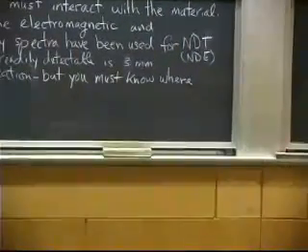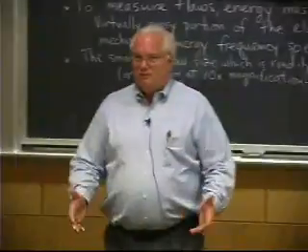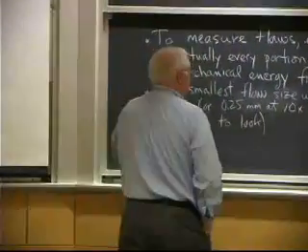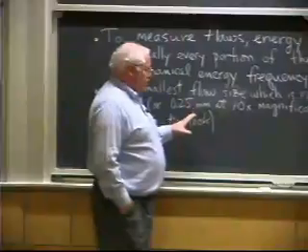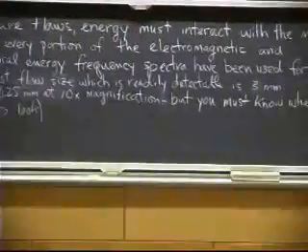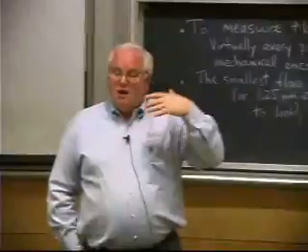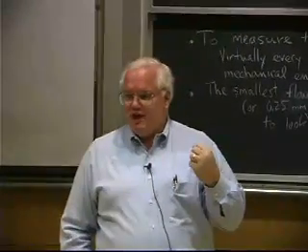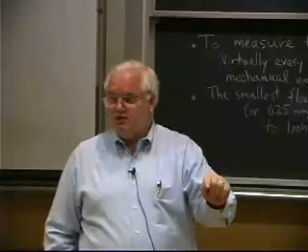You have to have some results in order to evaluate them, right? The smallest flaw size which is readily detectable is about 3 millimeters. Let me back up. When you're doing these tests, usually you have a human interface that has to look and say, is that really something on the radiograph?